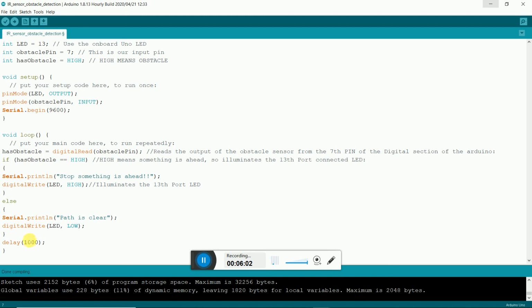As you can see, the process will be done step by step. Now here there are two things. One is the tick, that is verify, and another is upload. The USB cable which you attached to the Arduino board, you upload this whole program via this arrow.